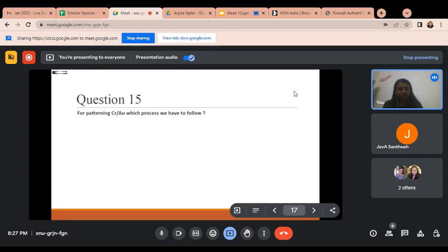I have already discussed in this class how to transfer the pattern from the mask to the photoresist layer. So which process will we follow? Lithography process. Okay, lithography process, but in which step? After the deposition of chromium gold, you have coated the wafer with positive or negative photoresist. Then which step will we follow? We will go for the soft bake.